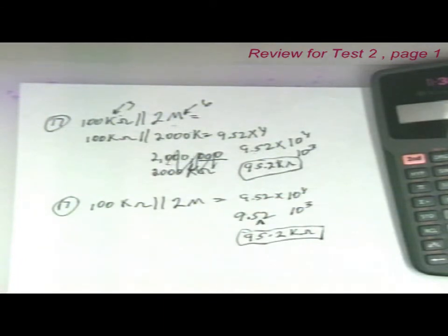If one resistor opens in a parallel circuit, what's going to happen to the current? The total resistance will what? Now we talked about this the last day of class. Remember, back on the bench there, we opened up some resistors. What happened? The total resistance increased, didn't it? In a parallel circuit, the total resistance increased, and the total current did what? Decreased. So when you open up a part of a parallel circuit, the resistance is going to increase and the current is going to decrease.